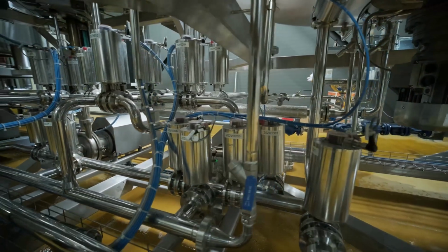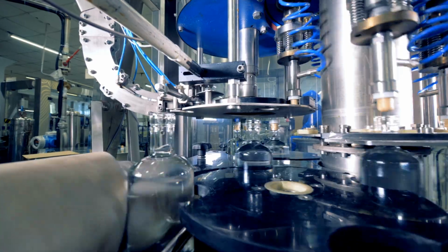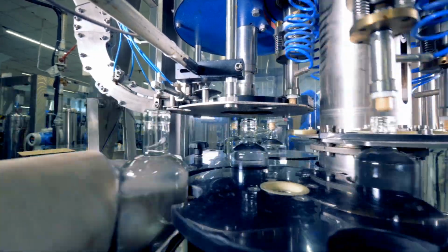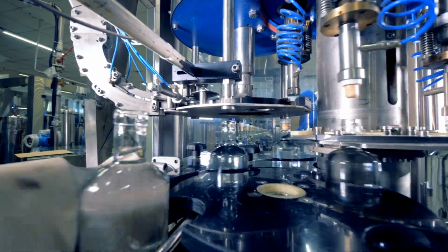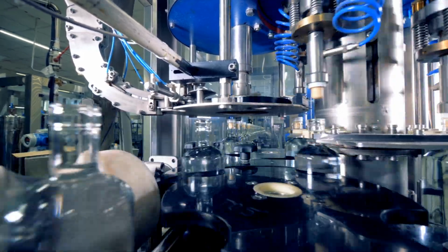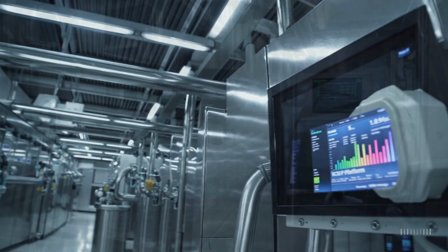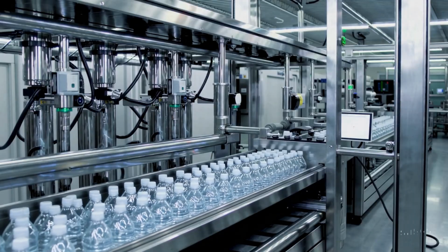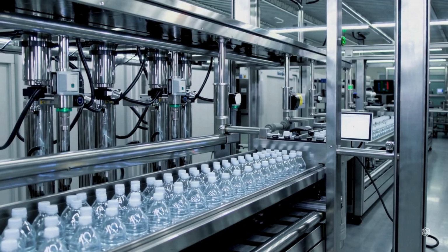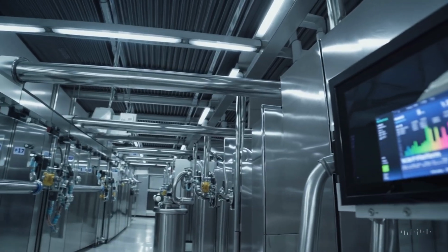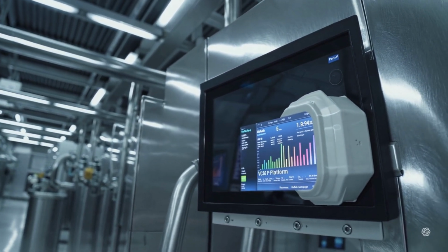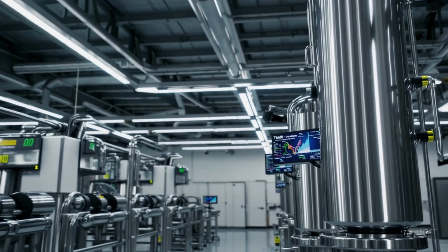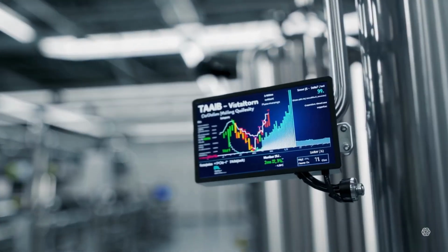Once the simulation is defined, the Smart Manufacturing module activates the virtual cyber-physical production system, vCPPS. It takes the simulation payload and deploys it into a live execution environment powered by MQTT, OPC UA, Node-RED, and InfluxDB. This module dynamically runs the virtual plant, executing the PLC logic, generating real-time sensor data, triggering actuator responses, and mimicking real-world operations with high fidelity. Therefore, let's now take you through this process visually.